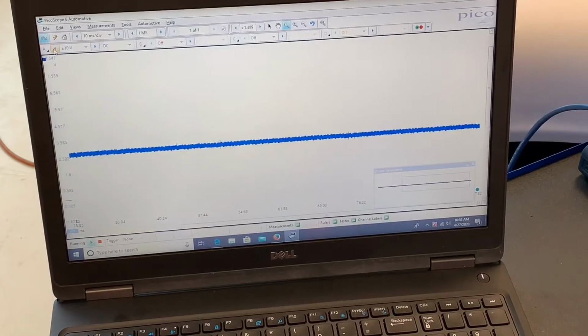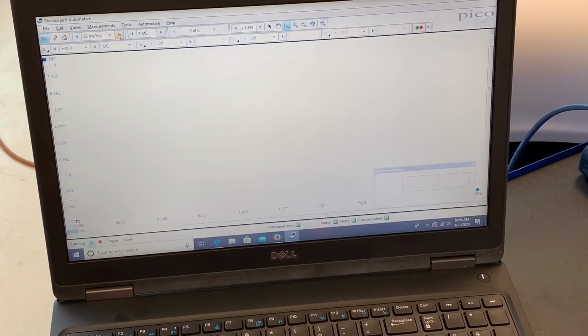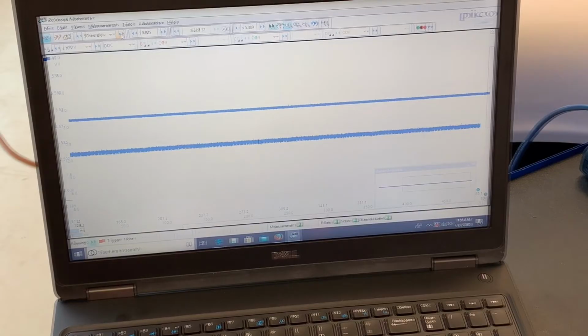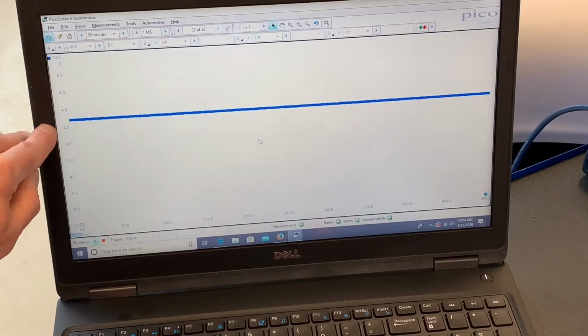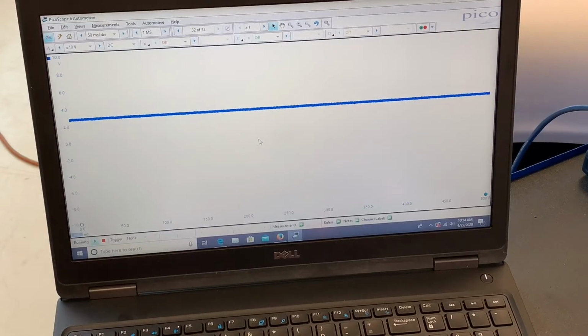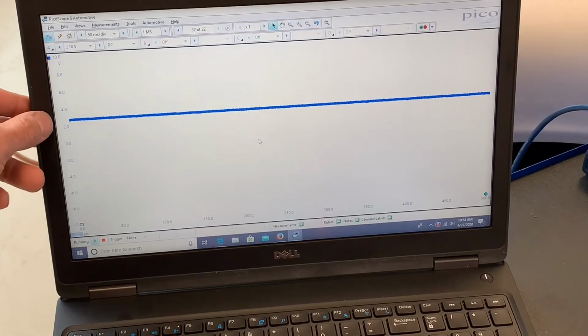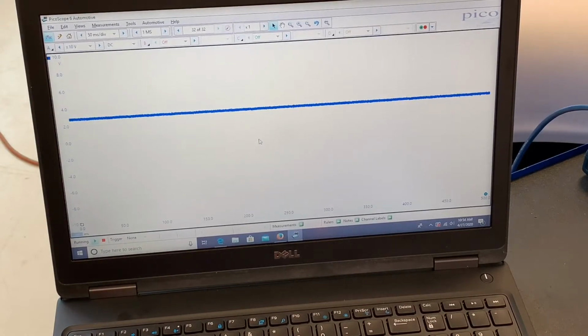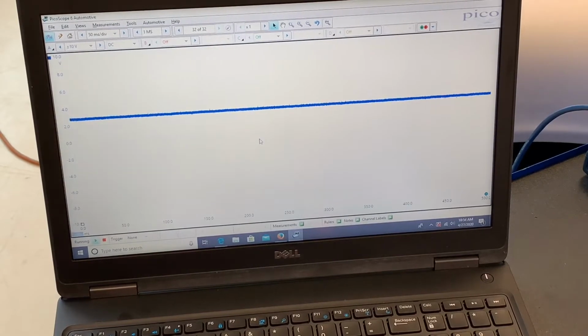We'll kick it over to a 10 volt scale and look at more time so that we can see what's going on. While that loads, we'll notice there's a big difference in this serial communication line versus the K line that we saw on the breakout box at the DLC on pin 7. This one is only running at about 3 volts, which is pretty typical. Serial communication is a low voltage communication, and so it utilizes a separate, lower voltage to make that happen.